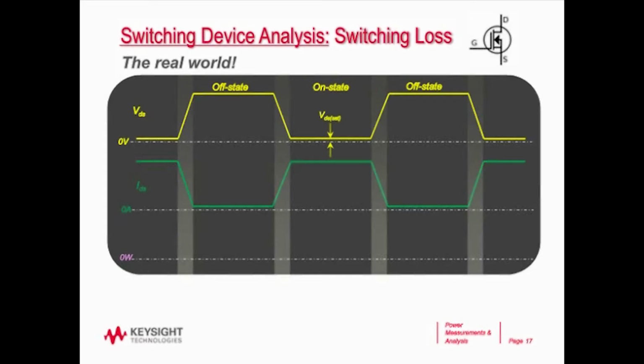During the off state, you may not measure 0 amps. Now, it will be 0 amps unless you have a problem with your switching transistor, but you may not measure 0 amps, and that's due to the current probe, typically the current probe or the scope null offset error.